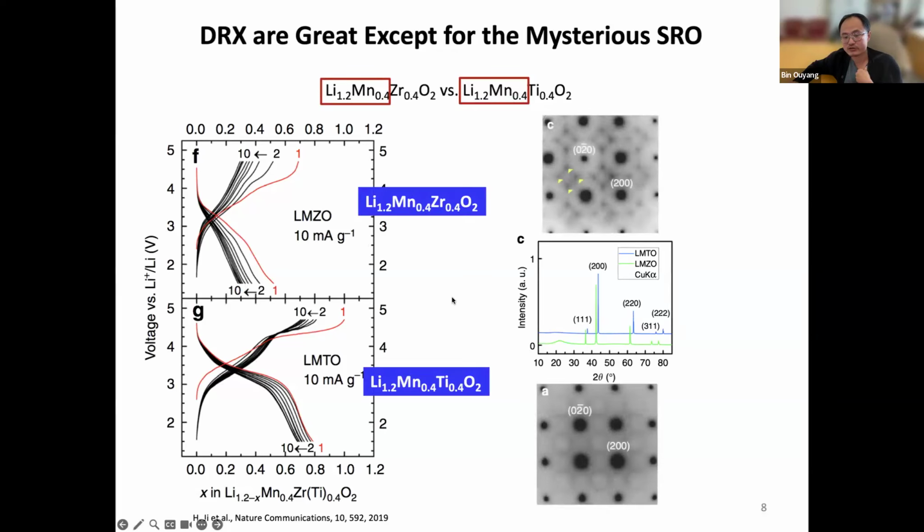Later, when we did characterization, a simple electron diffraction told us the differences in structures. They have very different diffuse scattering features. The Bragg peaks are exactly the same because they have an FCC rock salt structure, but they have totally different diffuse scattering features. Those are something called chemical short-range order. It's actually well studied and well observed in alloy systems.